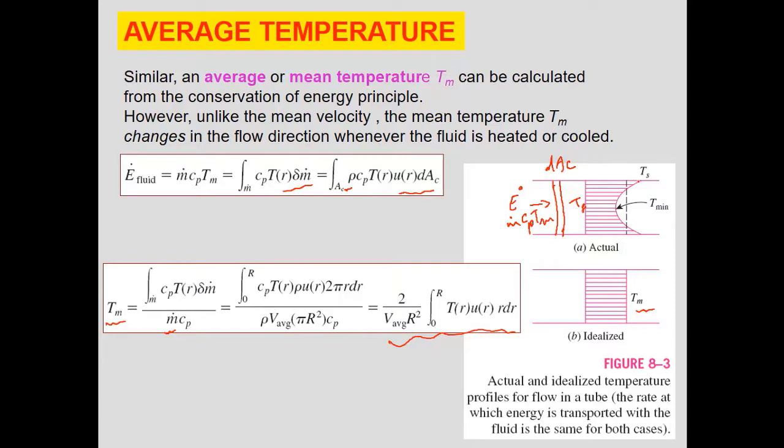The temperature of the fluid near the surface is equal to the temperature of the surface, Ts equal to T fluid. And in the middle, imagine here Ts is higher than T fluid. As we go further from the surface of the pipe, the temperature will be different. Here it is lower because the temperature of the fluid is lower than the temperature of the surface.